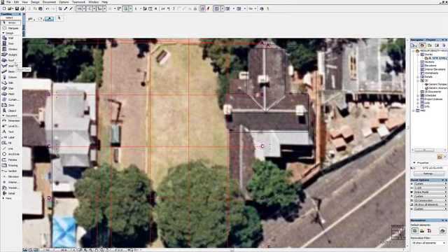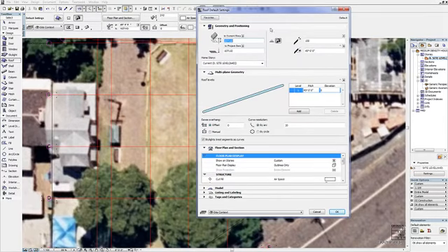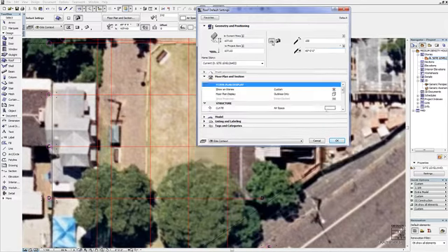So if you go into the roof tool, we can leave the RL to project 0 at 107,110, which is what it's defaulted to. The roof thickness is again 150. The angle of the roof is 45 degrees. Now, we don't want the multi-plane geometry. We actually want this geometry, which is the single plane. So we're going to click here. Notice how the multi-plane geometry area of the roof default settings has now grayed out.